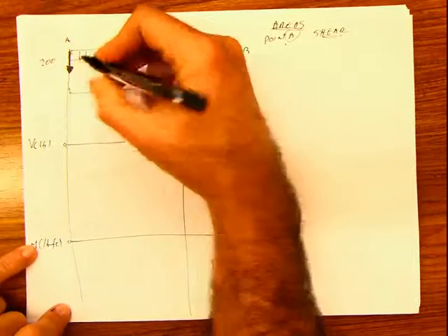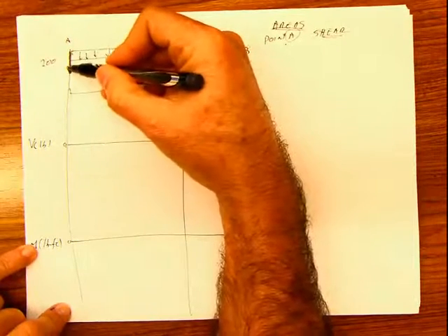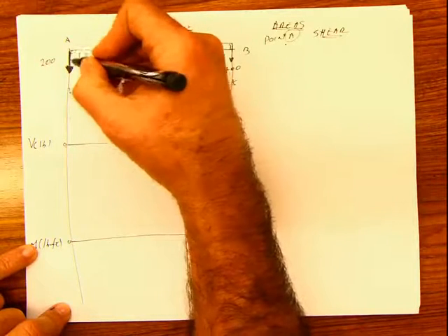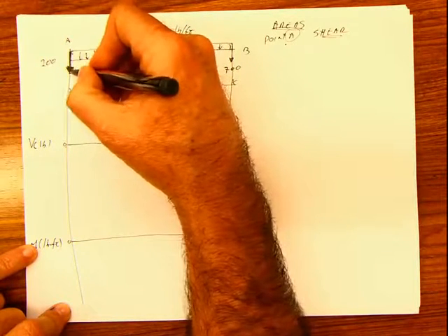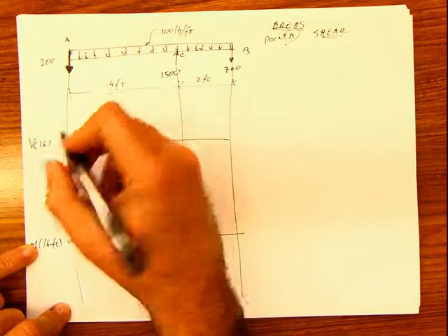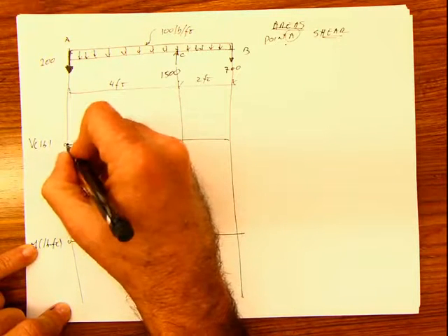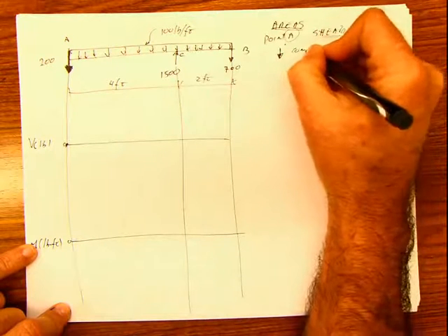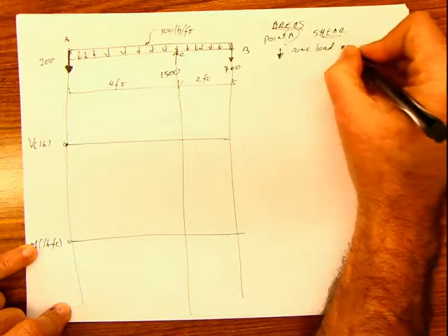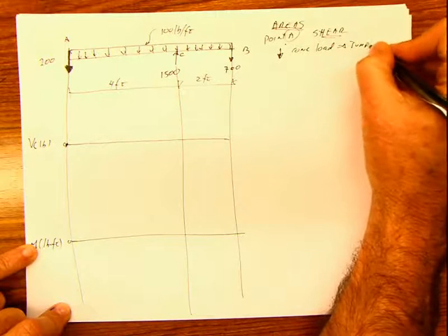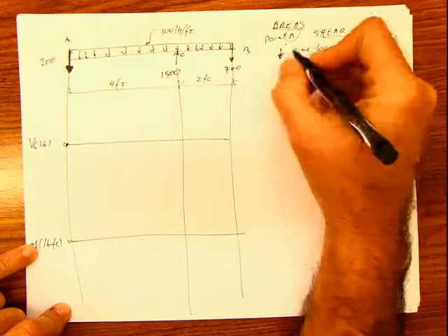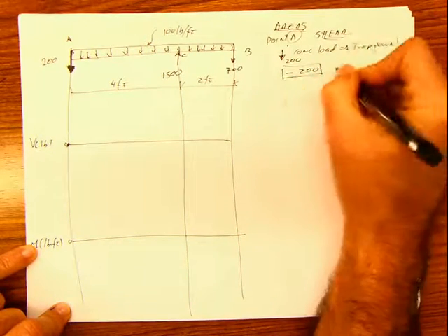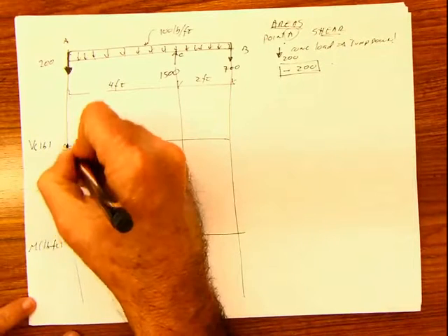It's a vertical force, which in this case is shear because the surface is horizontal, so it's perpendicular to our beam. This is a shear force of 200 and it's pointing down. That means that exactly at that point, my shear has to jump 200. So what you're going to do is concentrated load, jump, down. Why down? Because the load is coming down, 200. So my value in my diagram is going to be negative 200 from here to here.